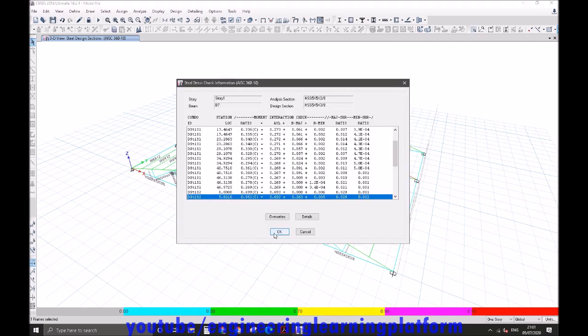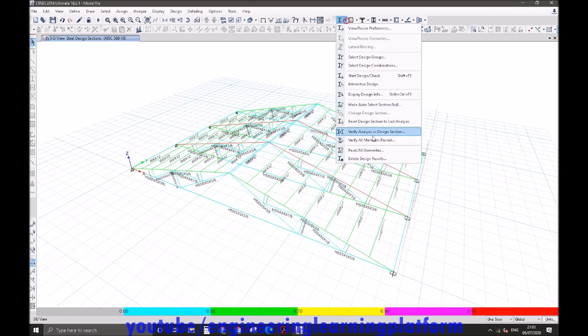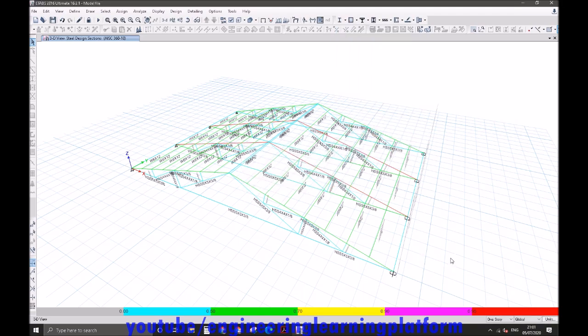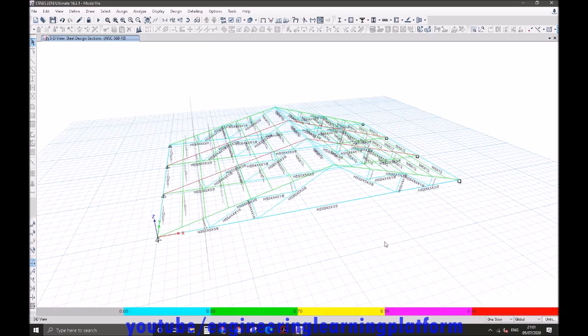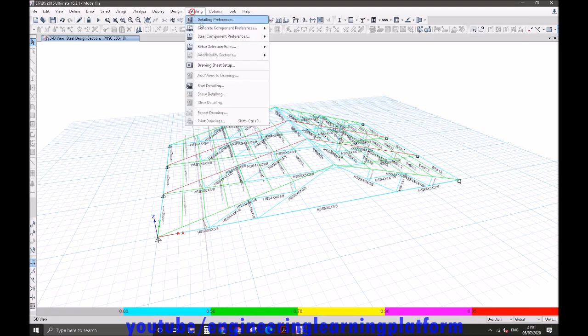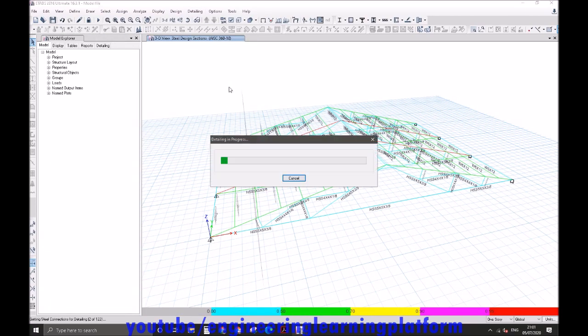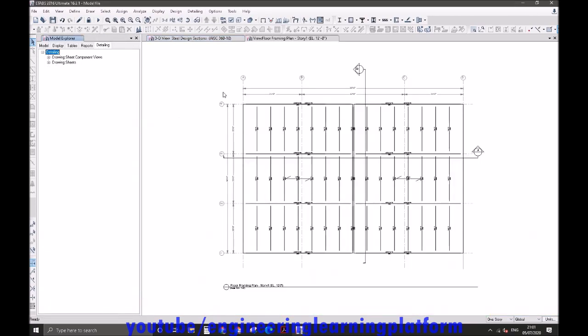So now all purlins have passed. You can see that we have passed the same size purlins as provided in the problem, with a 0.96 stress ratio of the center trusses. We have passed the center chords at 5 inch by 5 inch by 3 by 8. And please note that the truss span is 90 feet and the truss height is 12 feet.